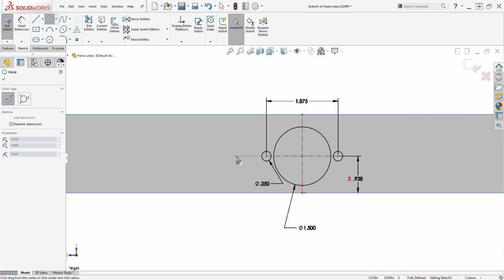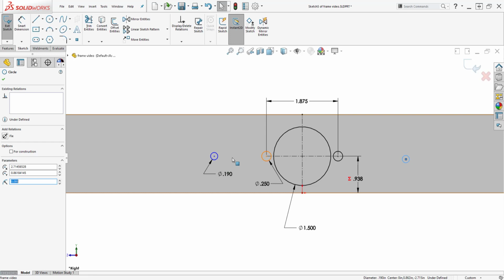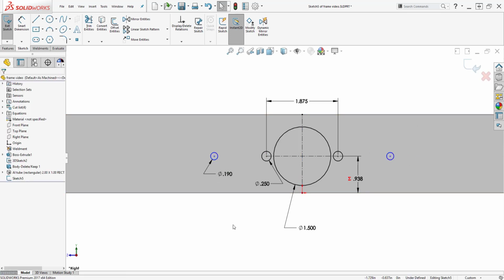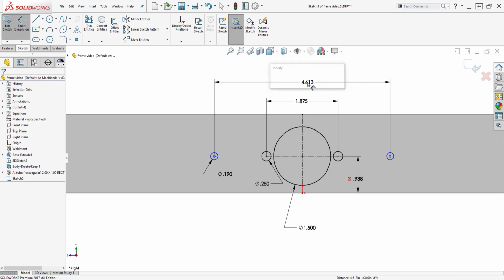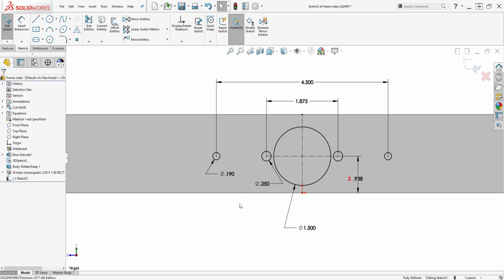The outer holes for the gearbox are tricky if you're not paying attention. Do not drill a hole all the way through this tubing before verifying the screw size you're going to use to mount this, because we want the screw head to pass through the first wall thickness of the tubing and sit on the second wall, firmly holding the gearbox in place. Therefore, you need two different size holes.